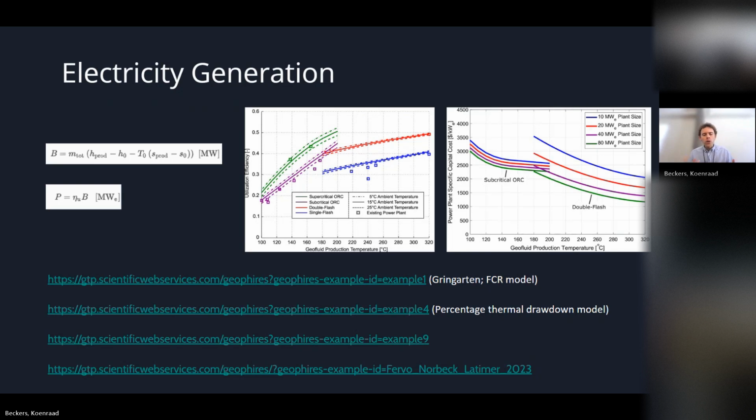So when you pick your subsurface model and you specify all your conditions and you simulate a fluid, water coming to the surface at a certain temperature and flow, etc., it's actually very fundamental things that are happening. It will calculate the amount of exergy that comes out of your well, because that is a thermodynamic property that relies on the built-in libraries that we're using. That will give you the maximum amount of electricity that you could generate with a Carnot type efficiency.